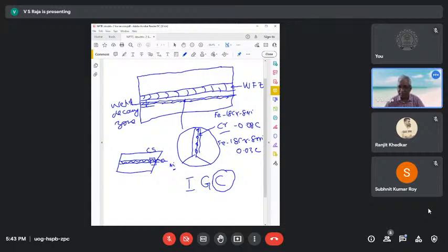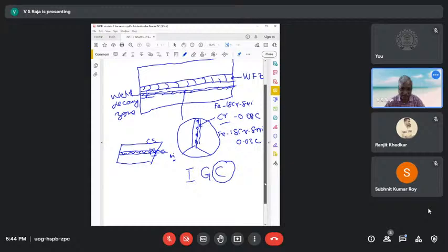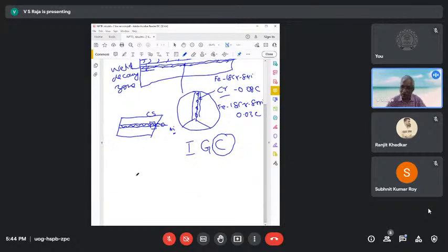So that means you understood why stainless steel passivates, right? Why does the stainless steel passivate? The stainless steel passivates because the corrosion potential lies in the passive region, right? So I'm going to draw this diagram here. This is your so-called Evans diagram or a polarization diagram, right? I draw this. What's the E, right?